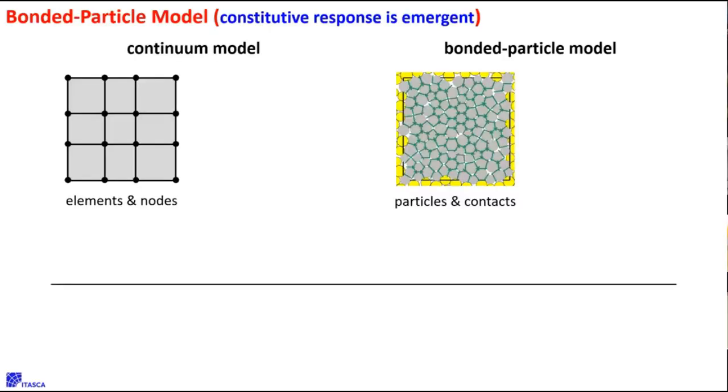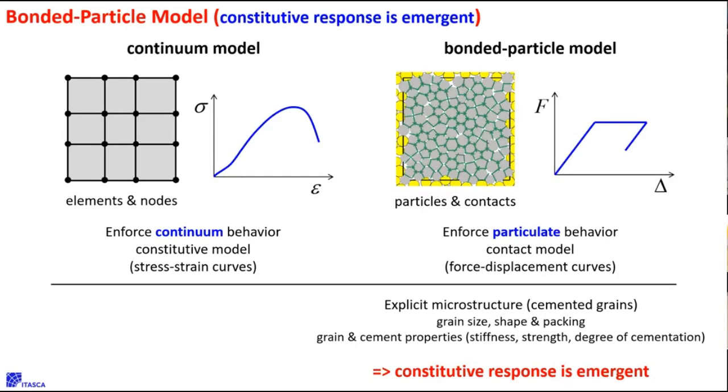If I use the FDEM to simulate an engineering scale model, how should I calibrate the contact parameters? Because the contact parameters are usually calibrated through rock samples, the particle size there is much smaller than in the engineering scale model, and the distribution is also different.